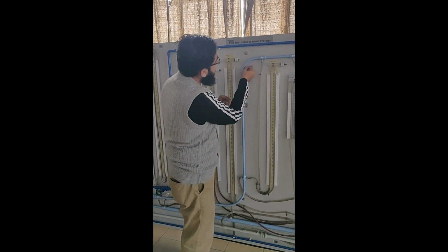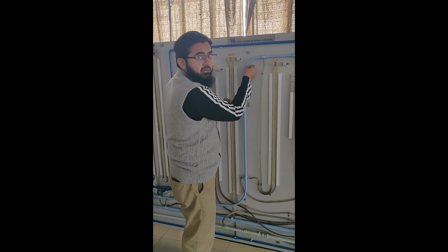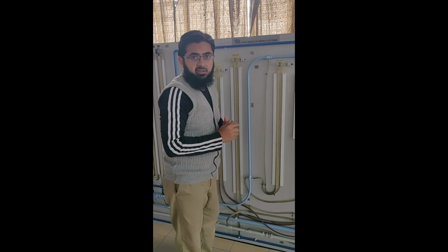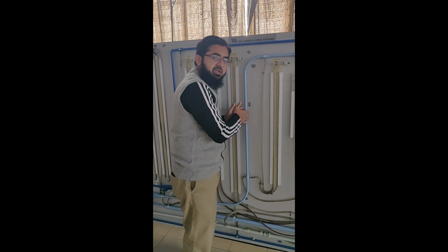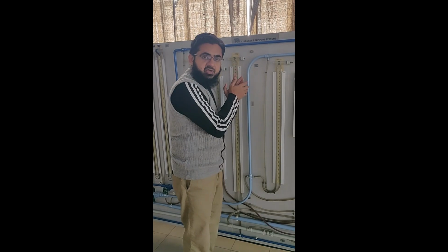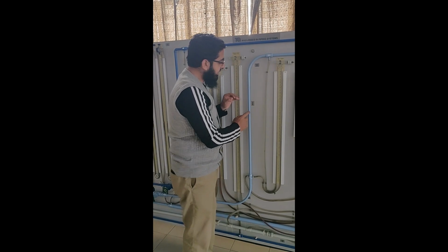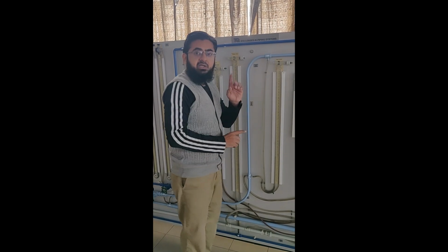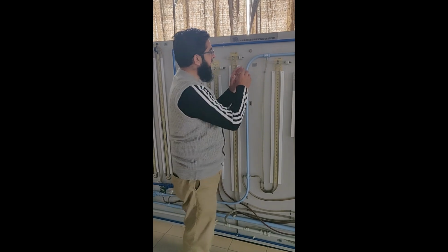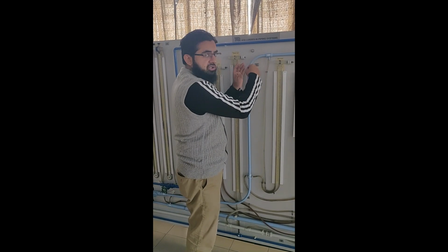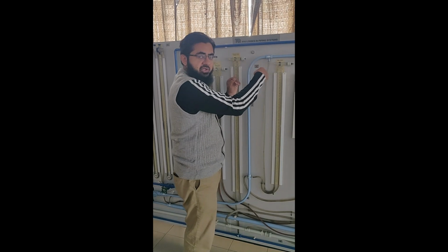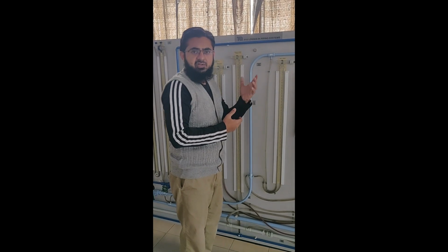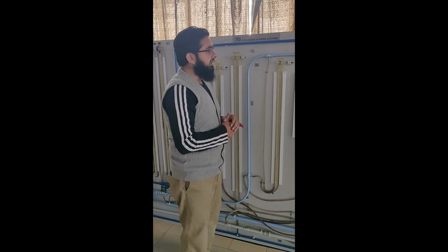So it's a possibility that there would be some kind of flow separation here. Now that depends on how much inertia the fluid has, and that depends on the velocity with which the fluid is flowing. That is one reason of losses. And because of separation, there would be a separation zone where there would be some kind of flow circulation, and that causes losses.